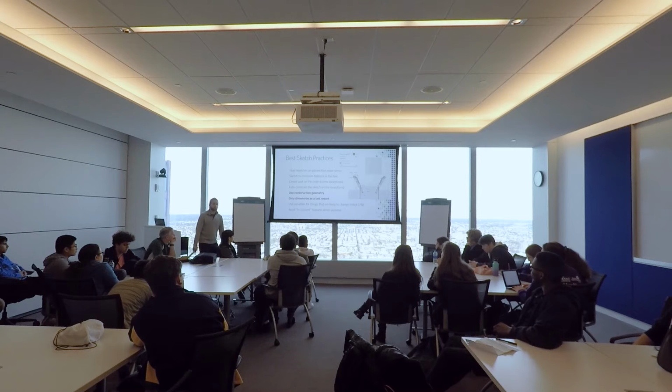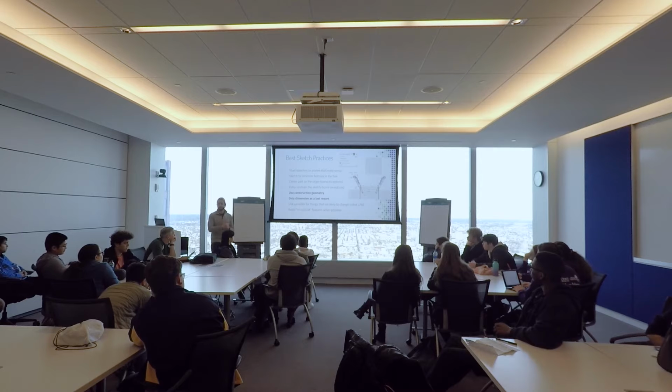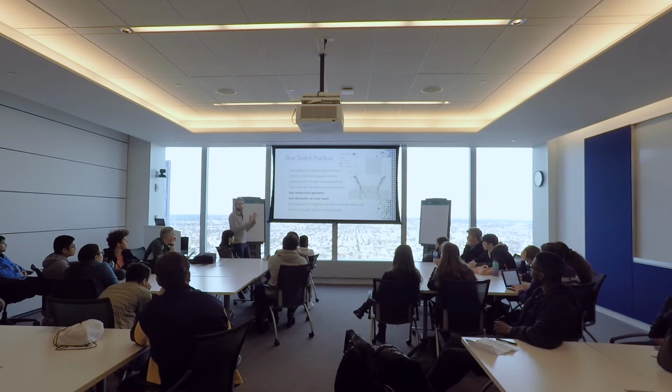So when I draw a robot, I won't necessarily start a sketch on the top plane. I'll usually start it on the right plane, looking at the side of the robot, so I can draw the wheels tangent to the floor, so that the robot's resting on the floor. That way your zero plane is actually zero, and when you do center of gravity calculations, they're from that zero plane. So you can know exactly where your center of gravity is relative to zero.